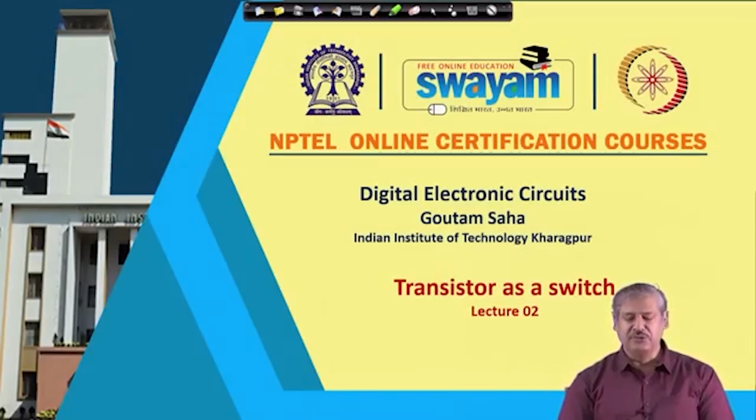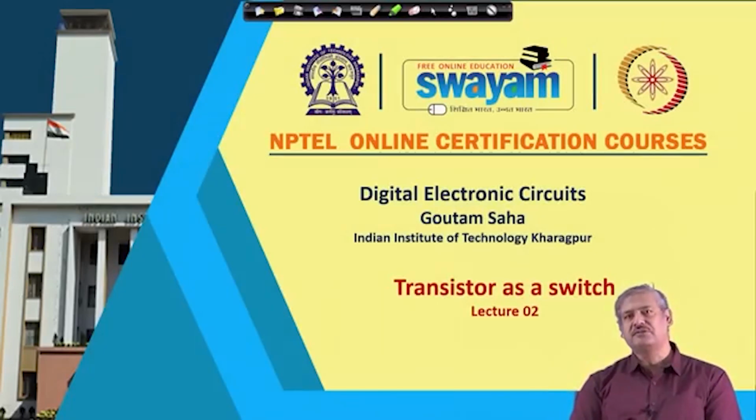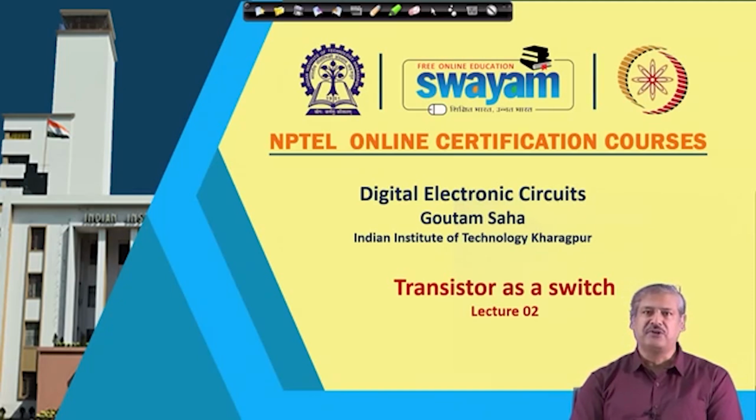Everybody, we move to lecture 2 of this particular course. In lecture 1, that is, in the previous lecture, we had seen why digital technology is important, what constitutes digital technology, the importance of switching, association of switching with logic relation, and use of diode as a switch. In that discussion we had seen that a diode as a switch can be used for developing an OR logic.